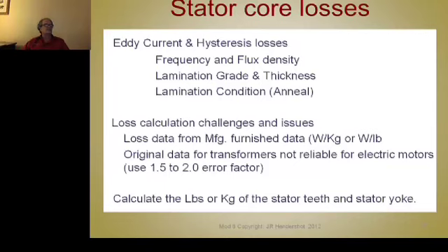These samples are like 12, 13 inches long and an inch wide, and so the percentage of the sample that's been work hardened by shearing is very small. Needless to say, they've tested samples that have been annealed and not annealed, and they don't find a whole lot of difference in them.